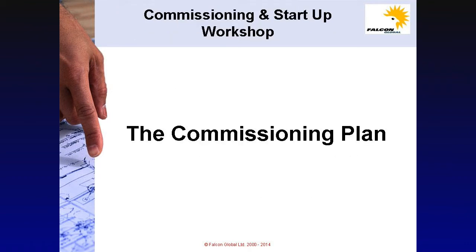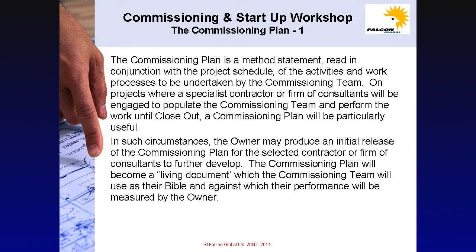The commissioning plan. The commissioning plan is a method statement read in conjunction with the project schedule of the activities and work processes to be undertaken by the commissioning team. On projects where a specialist contractor or firm of consultants will be engaged to populate the commissioning team and perform the work until closeout, a commissioning plan will be particularly useful.